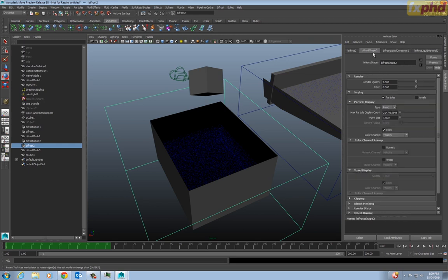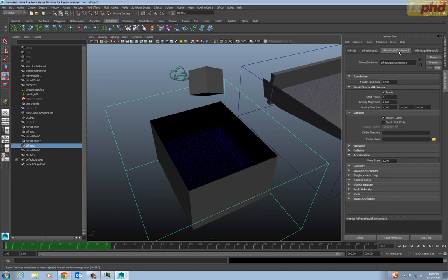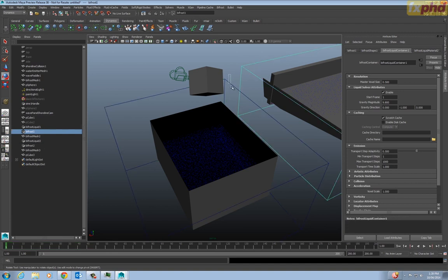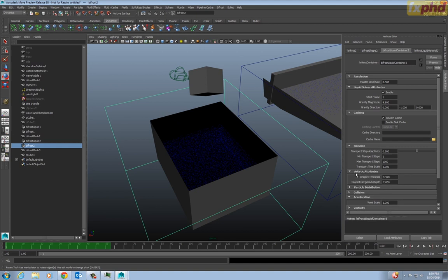We can see our voxel size here is 0.5, which is 50 times larger than the recommended detail level for the water. But it's really fast to simulate, but you have to have a trade-off between being really fast and being really undetailed. So it's kind of like honey or glue.